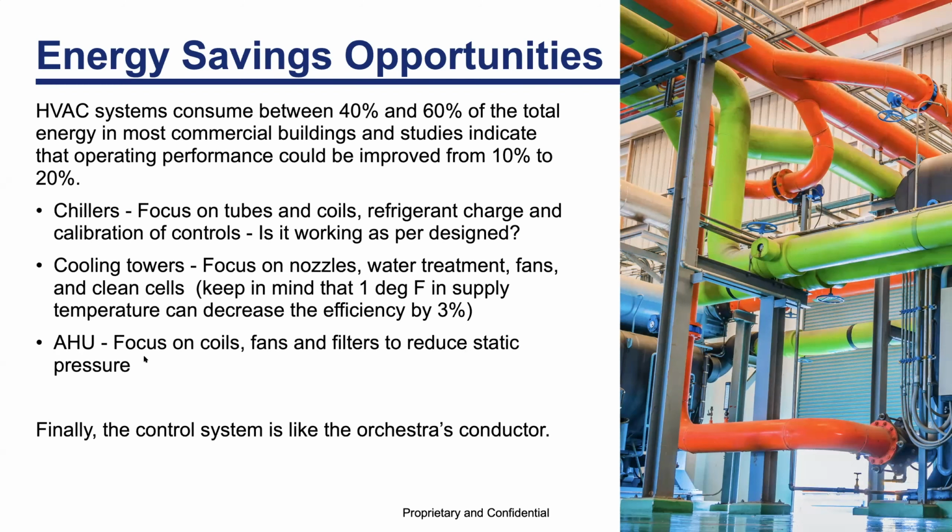Finally, the control systems. The goal for any chiller plant is to meet the building load. We all know that. The control system plays such an important role in the optimization process, but probably more important is the operator who is in control of the controls. If the operators are not instructed about how the system and controls should work, the system will operate in manual mode for the most part.